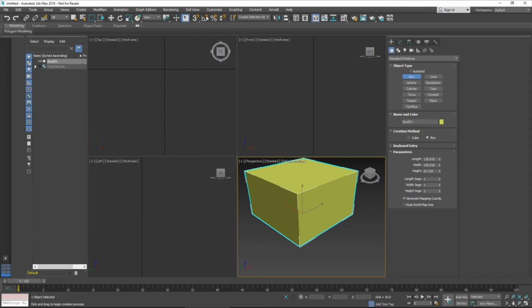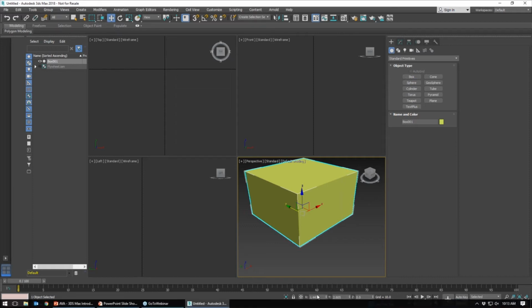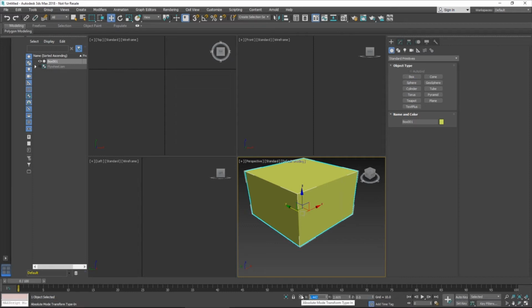First, we're going to move this to the 0, 0, 0 location. If you select and move again, down here you can input the coordinates you want to move it to. So X, Y, and Z all set to 0. Now I know my box is centered about my origin. You can toggle this to be relative instead of absolute coordinates, so you want to move it X distance or Y distance. You can select that if you want, but I actually do want the absolute coordinates.